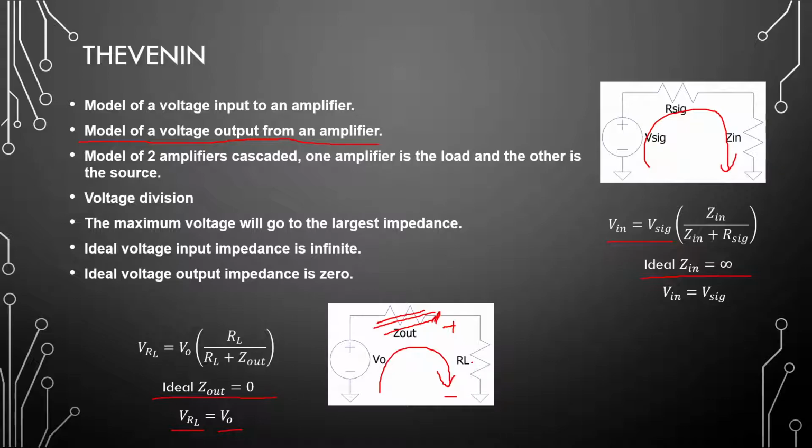One that is the ideal voltage amplifier would be the common collector amp, but it has no gain. The gain is 1. So that is more of a driver circuit. But its output impedance is low, so it ideally can drive a load.